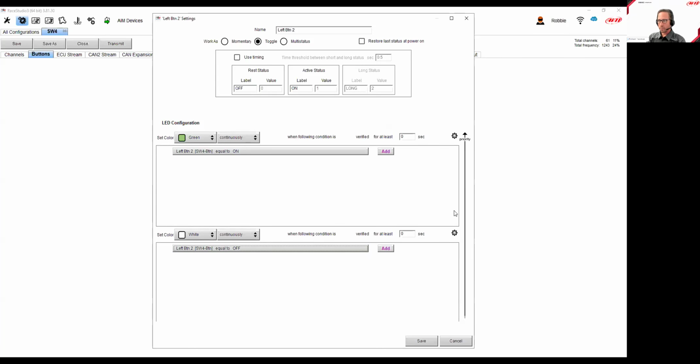Or because this is set up via priority, this can actually be always true, which is sometimes a little easier on the programming side of things. This is always true unless the button is on, in which case it turns green. So this logic overrides the always true logic. That priority thing is something we've been using for quite some time, and a lot of people don't know about it. And I'm glad you mentioned it, because that adds even more power to what you're doing.